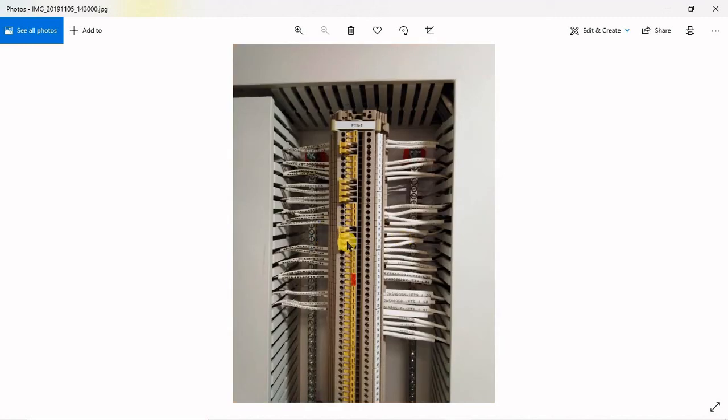These are disconnect terminals, just to show you that we have plenty of space here and it's very nice, and we also have all the wiring shields that should be connected here. So all of these, let's say if this is 4-20 milliamps or analog input, we can connect our cable shield in these connections here. So that will save space in my cabinet. But the terminals are all elevated a little bit, so they will not interact with your ground. And the other thing is that this will save a lot of space for your cabinet.